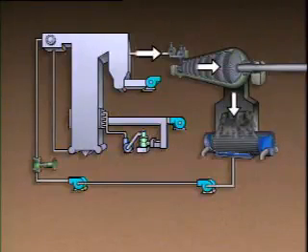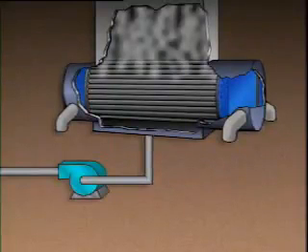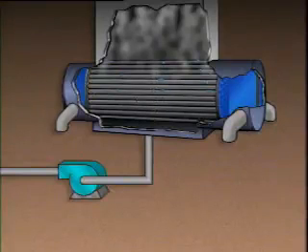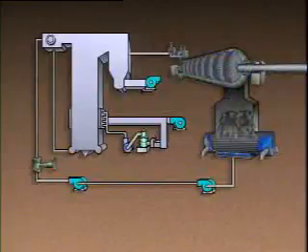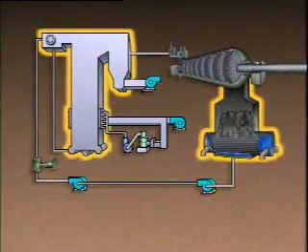When steam first enters the condenser, it fills the available space. But as the steam condenses, taking up less and less space, a vacuum or negative pressure is created in the condenser. This negative pressure tends to draw more steam through the turbine and into the condenser. Once the steam is condensed into water or condensate, it collects in the hot well. Now the condensate has to be moved from the low pressure area in the condenser back to the high pressure area in the boiler.